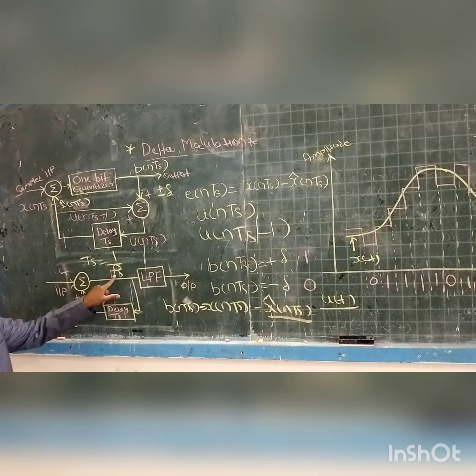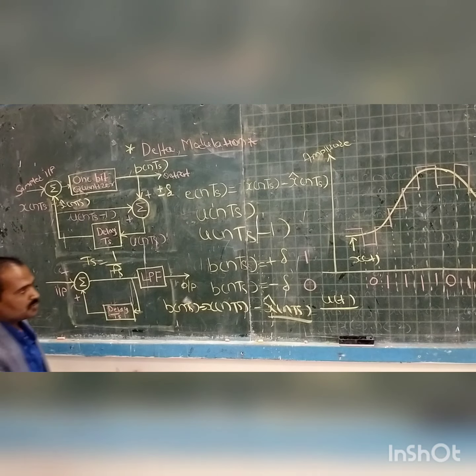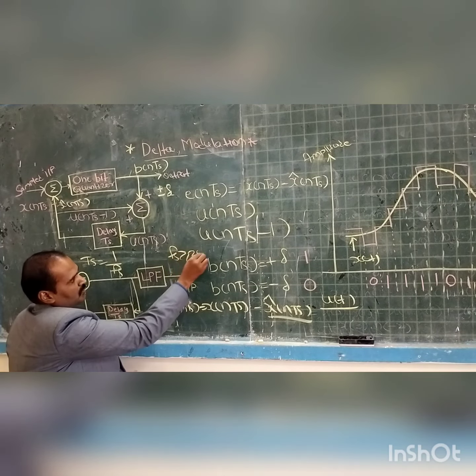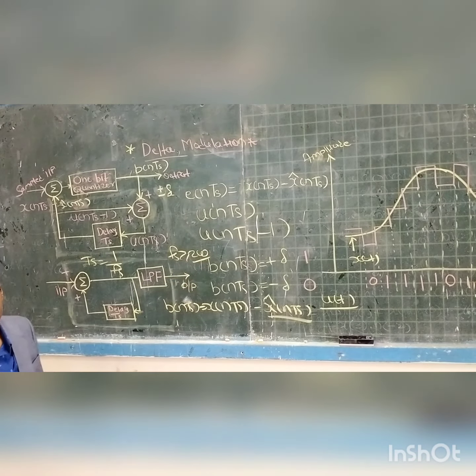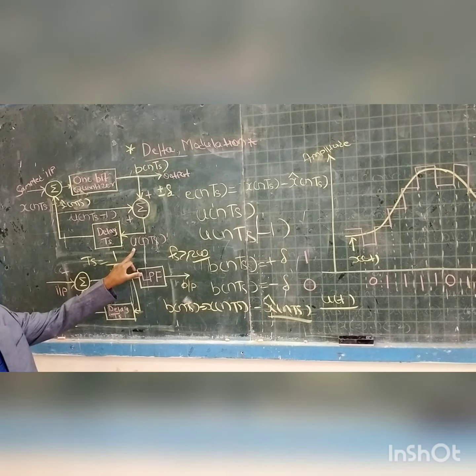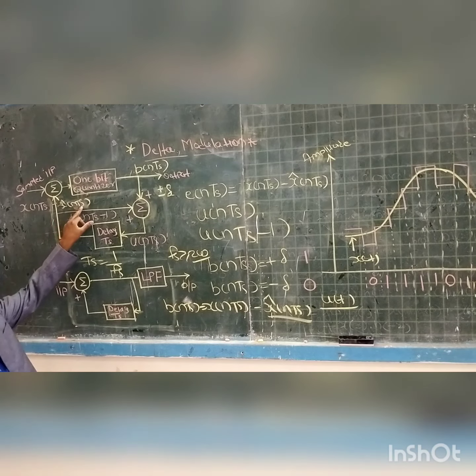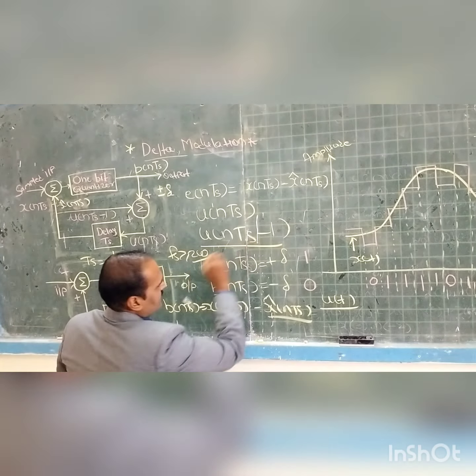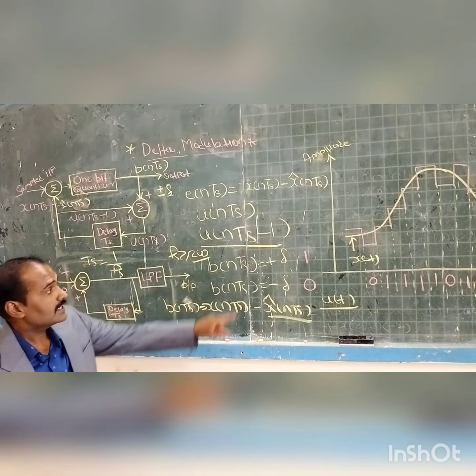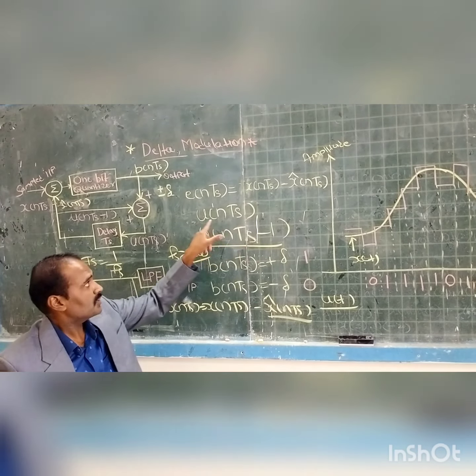According to the Nyquist criterion, or the Nyquist rate, the sampling frequency Fs should be greater than or equal to 2 omega, where omega is the highest signal frequency component present within that envelope. So that much delay is added to which signal level? To the present sample value of the staircase approximated signal to generate x cap of nTs. As you can see, x cap of nTs is obtained by adding a certain time interval with respect to u of nTs.